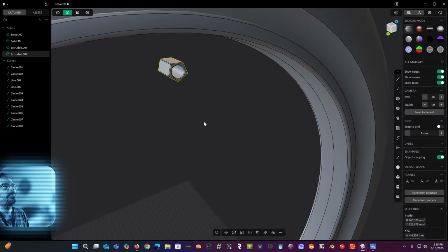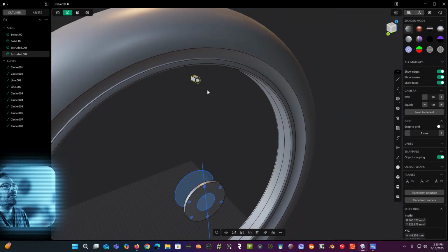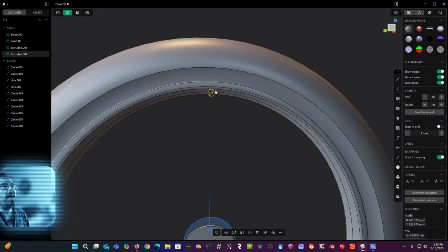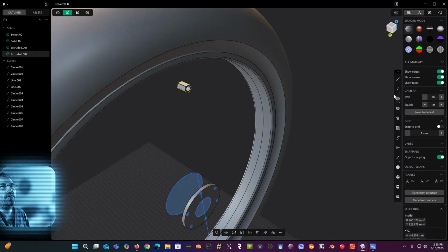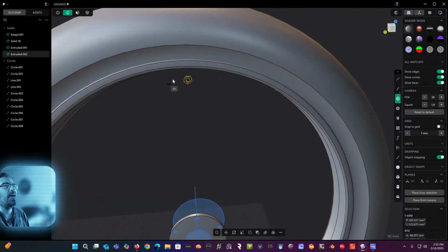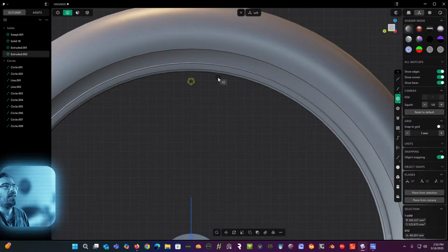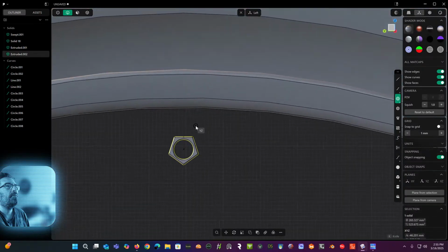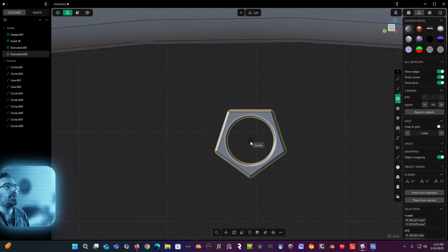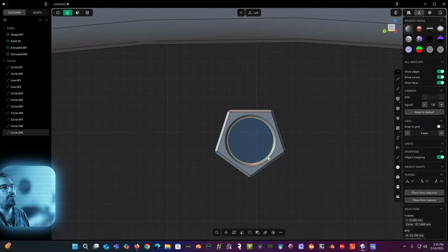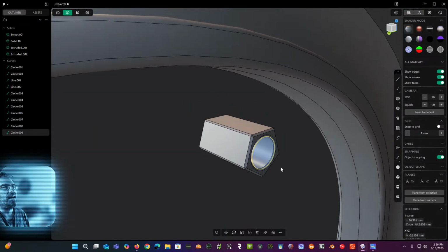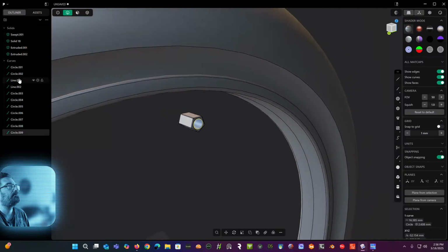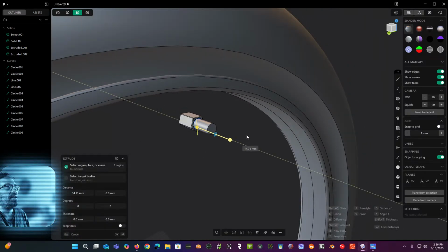That's literal. And now I've got to figure out the size of my actual spoke, which will be easy because now we have this circle we've just made. So I'm just going to come up here. Could have gone to the bottom too. And I'm just going to make a circle. And then this one we can now extrude out. We're not going to do it fully yet, because I just want to grab a piece of it.